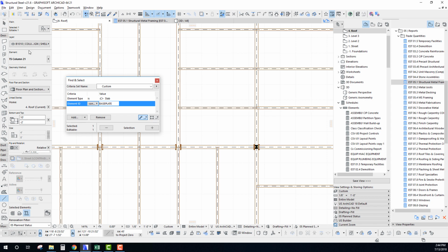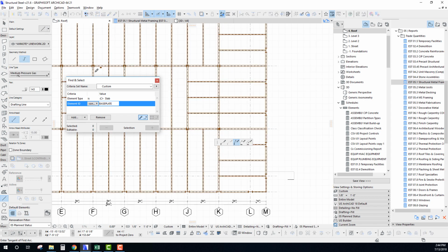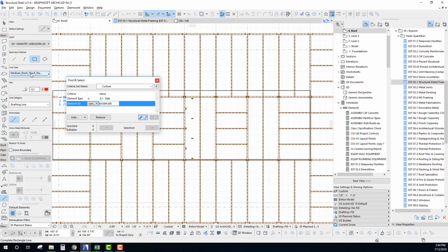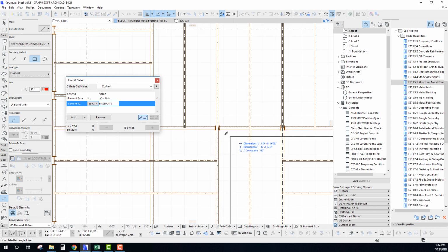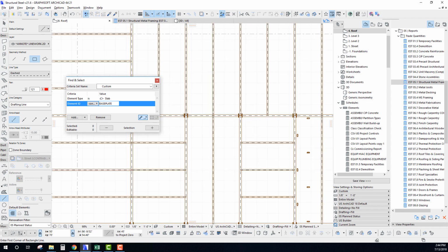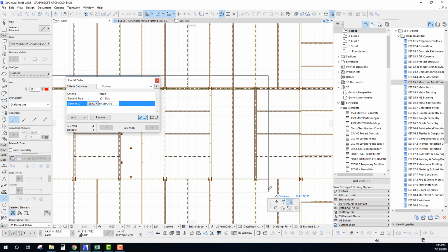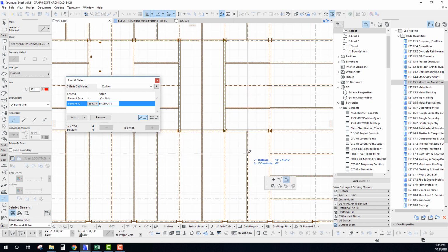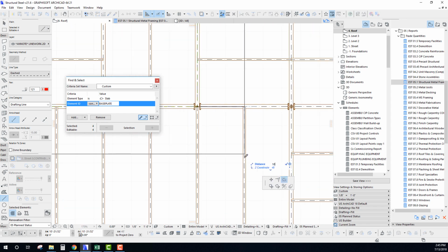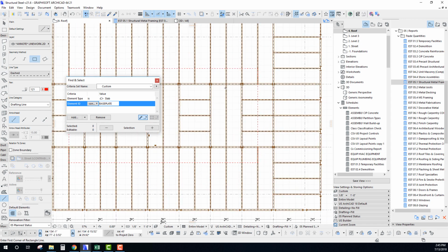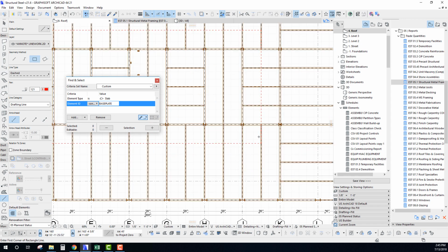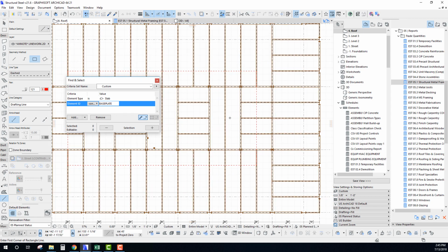So what I might do, actually, this is a nice reason for drawing in just a reference line. I'm just going to change my settings here. Let's make this red so it pops out. And let's just draw in about where we think a mechanical screen might go. So maybe from there to there. I'm going to undo it, redo it, just to select those, undo or suspend my groups. And maybe if we push this out 10 feet, that kind of gives us a nice clean line for where we're targeting with our mechanical screen here.